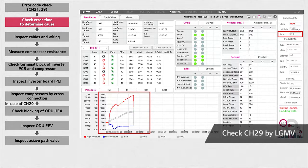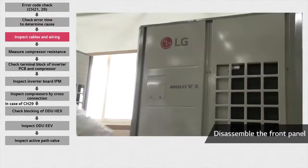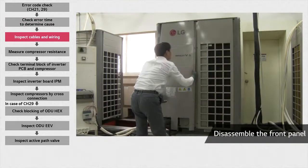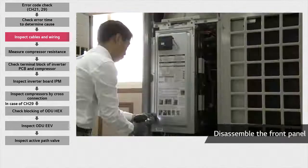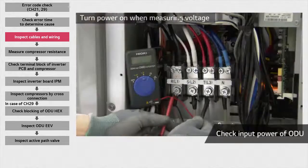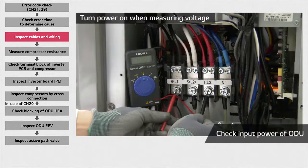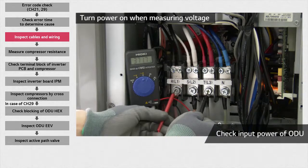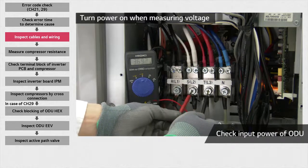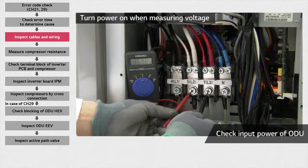For a more detailed explanation regarding this issue, please refer to the following steps. To carry out a closer inspection, start by disassembling the front panel of the outdoor unit. Then disassemble the control box cover of the outdoor unit. Their value should be 380 volts. And RN, SN, TN are the phase voltage. Their value should read 220 volts each.